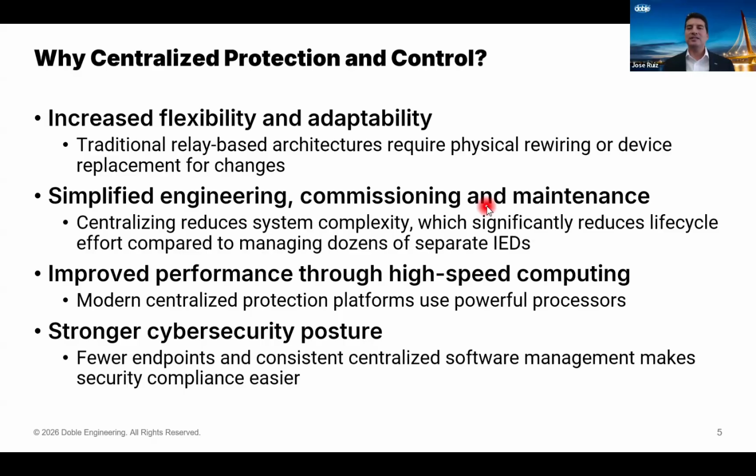No doubt, a computer server has a more powerful central processing unit, or CPU, compared to the microcontroller in a microprocessor-based relay. The algorithms are the same, by the way, because what we are doing in the microprocessor world is basically mimicking the algorithms that electromechanical relays have been performing for decades, as logic in the microprocessor-based relay. The same logic that is available in the microprocessor-based relay is now brought into this computer server, or microprocessor-based device, that is used as a centralized protection device.